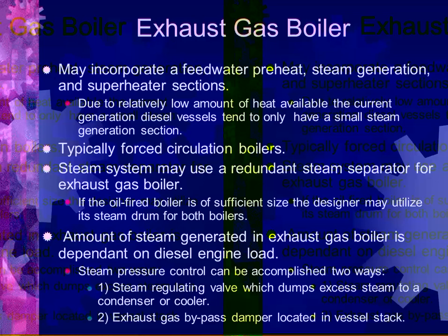If you have a large enough engine and you're producing enough heat in your exhaust gas, there's enough heat transfer to the exhaust gas boiler. I don't know the exact dividing line, but it's about 60 megawatt, it seems to be. Then you're going to go into a combined cycle and have a steam turbine that will take the heat that you have above what you need for heating services and use that to generate electricity.